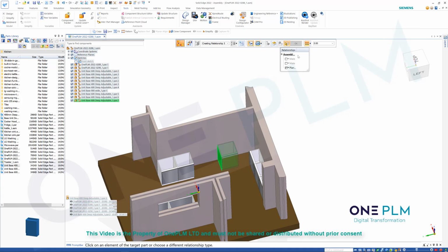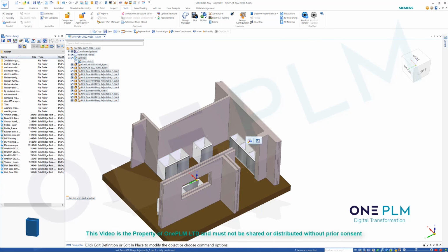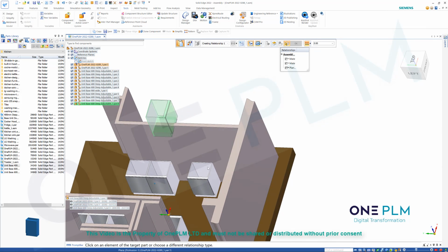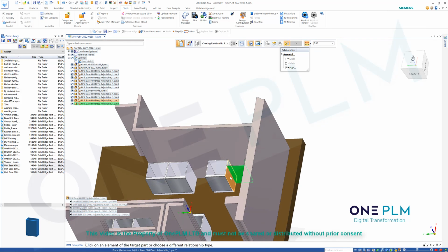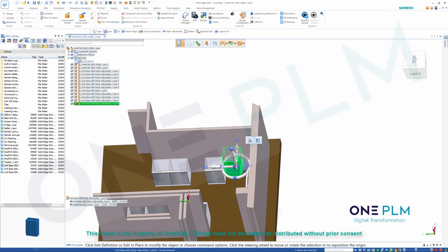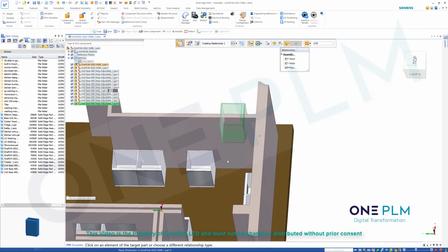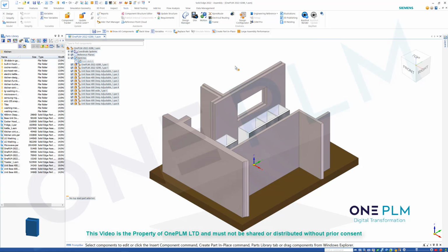We're going to have the oven in there, so I'm going to do a 600. So for this one, I've got a tall unit, but I've actually got a nice oven unit on here. So I'm going to paste these, and then side. If you do click the wrong relationships, easiest thing is normally just to bring it back in on there. Okay, so now we've done that. If you do Control I, that takes you to an isometric view before you save. Always a good way to make sure it looks nice before we save that.